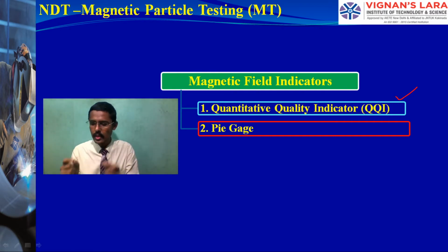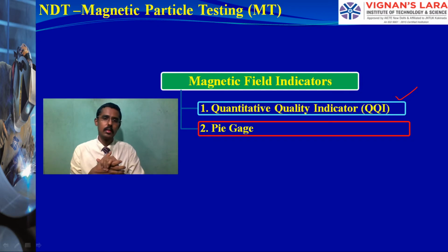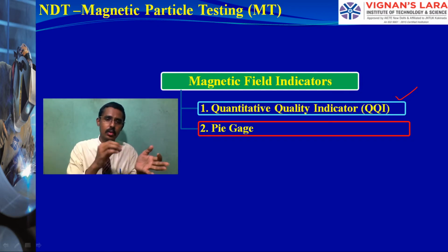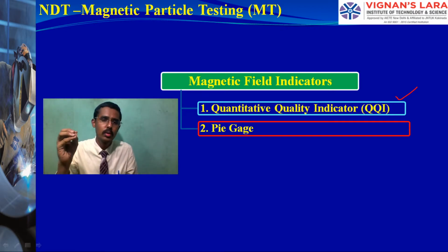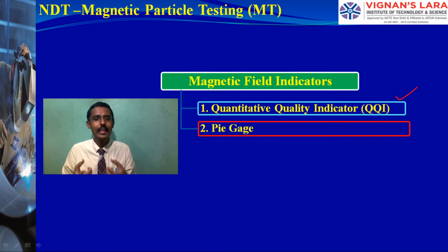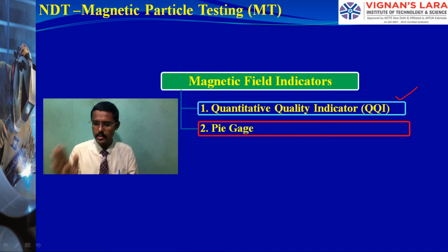Otherwise, we will get doubts whether the crack is present or not present. Whether the process is done, and the supplied current makes the proper quantum of magnetic field. The quantum of magnetic field only attracts the particles that we are pouring over there. Therefore, we will get a doubt in doing inspection whether the method is done correctly or not. Therefore, we need a calibration setup to calibrate. Yes, it is correct. Then whether it attracts or not attracts. If it is not attracted, no crack, no discontinuity is present. If it is attracted, yes, there's a crack. We can justify. So the first point we need is to identify whether it is calibrated, it is standard, it is correct or wrong.